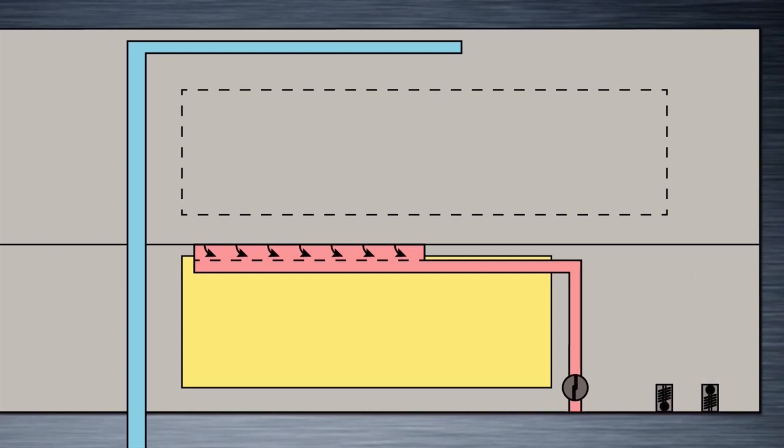On the other hand, a single negative pressure relief valve located aft on the lower left fuselage protects the airplane's structure from being damaged by negative pressure differentials. This is especially important during a rapid descent, such as after a rapid decompression. When pressure outside the aircraft is 1 psi more than the cabin pressure, the negative relief valve opens. Notice that this valve is independent from the 737NG pressurization system, and it requires no crew action.